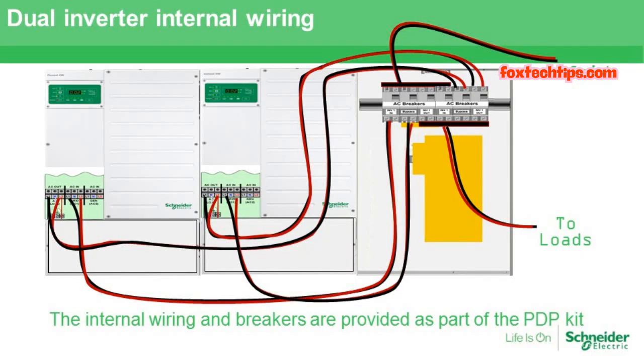When looking at the basic building blocks for an AC coupled solution, you do want to check with the manufacturer of the inverter to make sure that it is compatible with frequency shifting. But one of the nice things about the XW Plus is that with frequency shifting, it will finally kick out at 60.5 hertz. But ideally, an inverter will actually listen to the frequency shift and actually diminish its output so that we get more of a controlled charge based on loads as well as whether or not the batteries need any charging or whatnot.